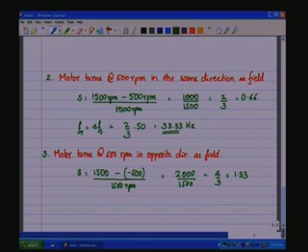So you see the slip is greater than 1. If the slip is equal to 1, there is no speed, the motor is at standstill condition. When the slip is less than 1, it is motoring. When the slip is greater than 1, it is braking. So whenever you have a slip which is greater than 1, it is braking operation. And whenever the slip is between 0 and 1, this is normal motoring operation.